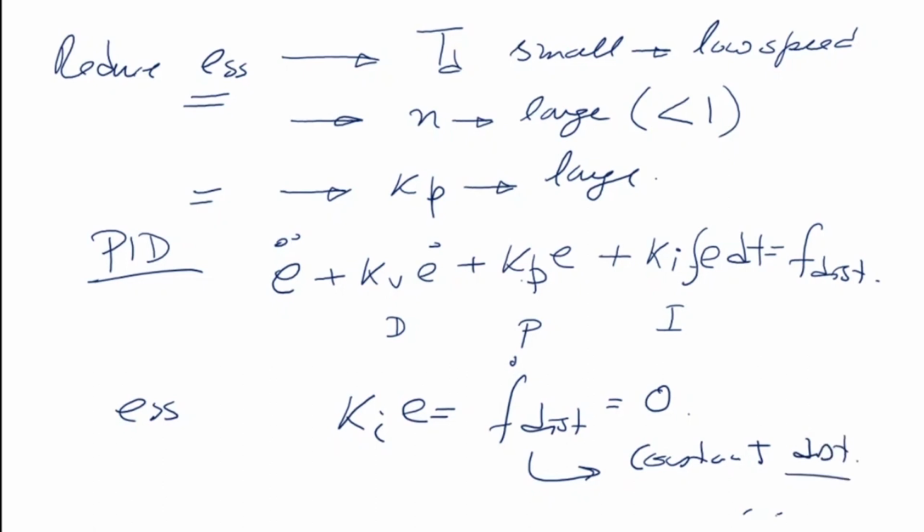So under this condition, the steady state error becomes 0 by putting an integral part into the controller. Now, the disadvantage of this is that we are making the system higher order, it is becoming s raised to 3. And for very, very high gains, it will become unstable, because the roots will move towards the right half plane.